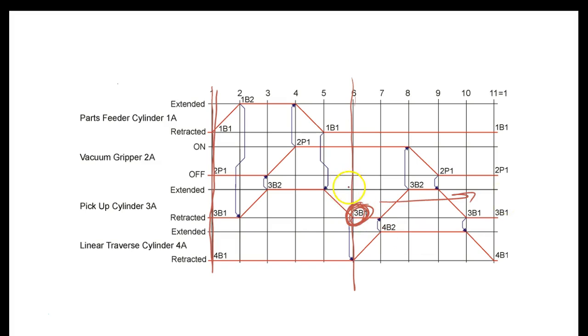Now we wouldn't move forward from that, but we might move backwards because 1B1 is required for it to do this, right? You understand? So if 1B1 fails, then of course the thing would never retract. If this failed, then the thing would never move because now it can't get pressure. If this thing failed, then the pressure would never come on. If this was on all the time, then odds are your vacuum pressure would come on instantly, because that's all it's probably looking for.